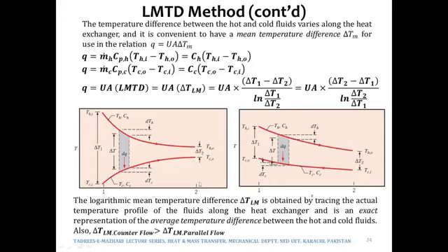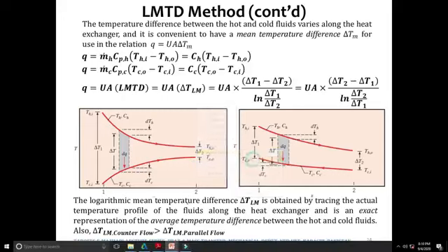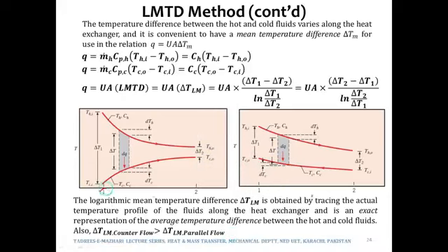This is section 1, and this is section number 2. At section 2 the difference delta T would be Th out minus T cold out, but this will not be the same as, for example, in a counter flow heat exchanger. In a counter flow heat exchanger, at sections 1 and 2, the delta T would of course be written in a different form, because of the very obvious and detailed discussion that we had for the last half an hour or so. So it may be written either in this form or in this form, it would not matter, right?